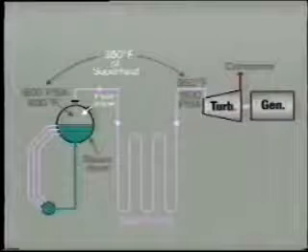Superheat is added in the superheater section of the HRSG. Steam from the top of the steam drum is fed into the superheater inlet header. From here, it passes through the bank of superheater tubes, which all discharge to a common superheater outlet header. From this common header, the superheated steam is piped to the steam turbine.